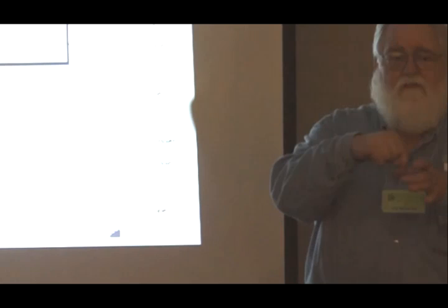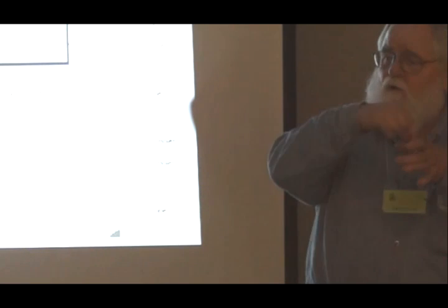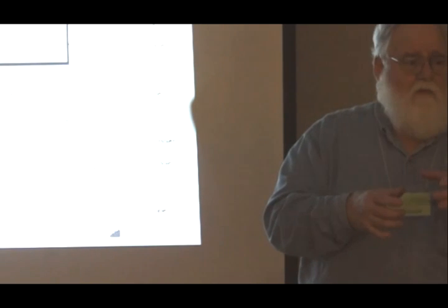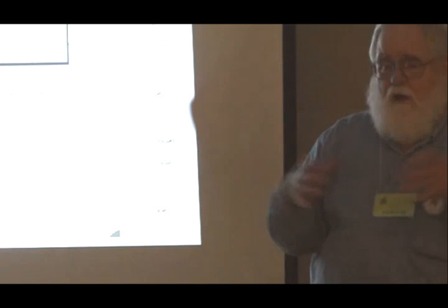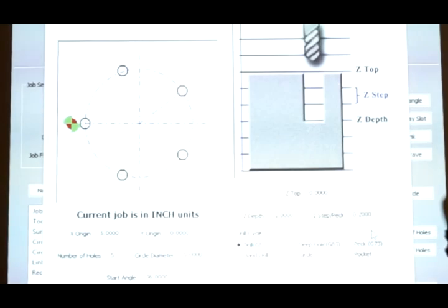All I can do is one circle cut around there and the tool will clean out my counterbore. But if I wanted a great big counterbore, I would choose the pocketing operation. And both of those wind up calling the exact same G-code routine that my cut circle and cut pocket use. So all that code is shared, and if I find a bug in it, I have to fix it in one place, and it gets fixed in both of the others.